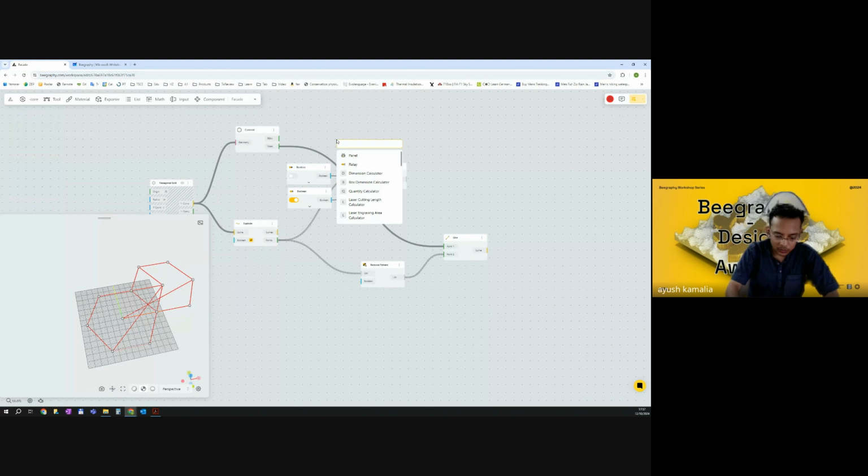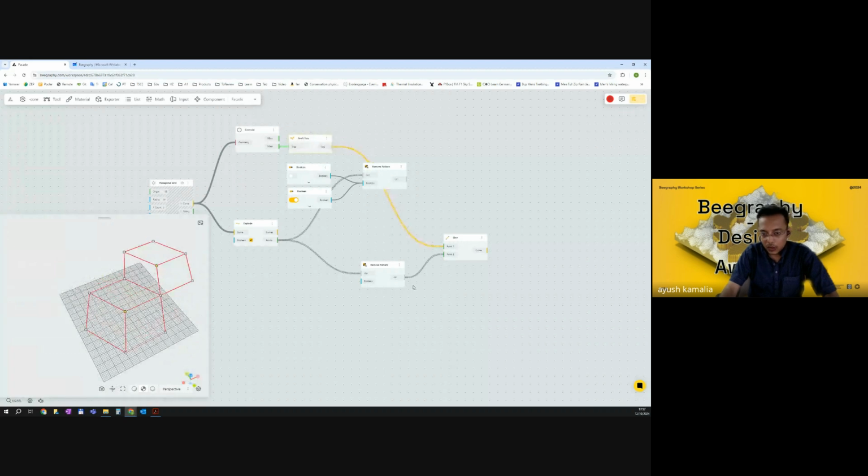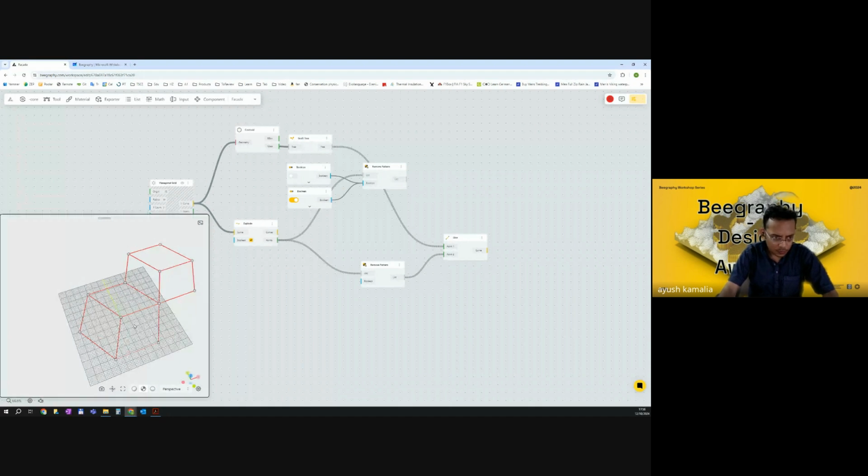So what we can do is graft the list into multiple branches, and that should help in segregating the points. And this is working well. What we did is, because our other input is coming as multiple branches of a tree, we have to convert it into the same format. Our data should be coming not as a single branch, but as a tree with multiple branches. And that is happening well now.